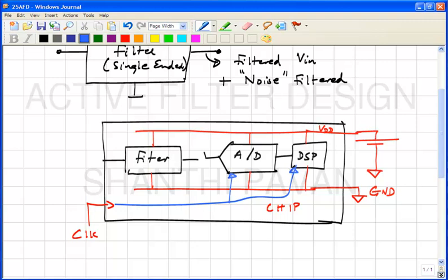So even those of you who have not undergone a digital IC class should be able to understand that a NOT gate consumes power only when it sees a 0 to 1 or a 1 to 0 transition, right? In a similar fashion, any logic gate built with the CMOS family will also draw current in spikes from the supply only when it sees transitions.